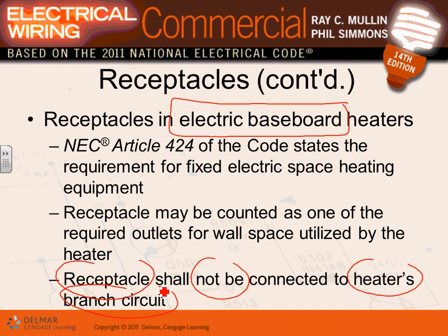And for the heater, fixed baseboard heaters, we size them at 1.25, and you guys did them with me, times the full load amp of that piece of equipment. And of course, that receptacle will act as a wall space receptacle, a receptacle for a wall space. Any comments, any questions?